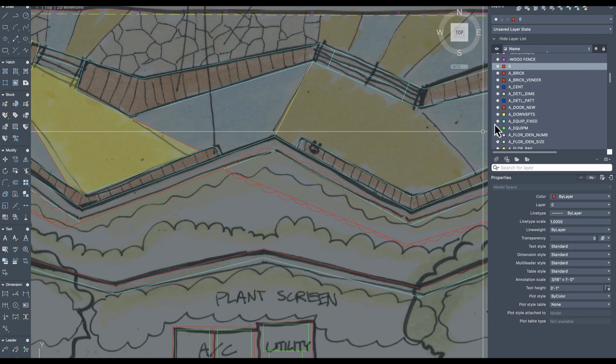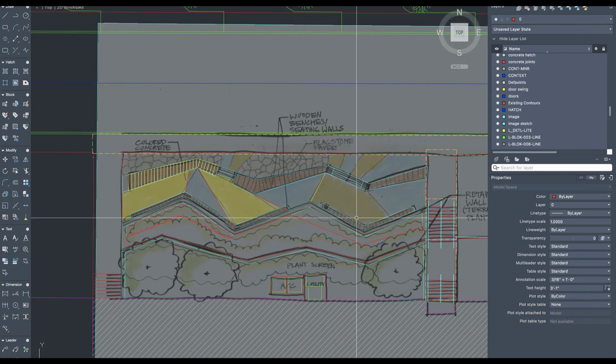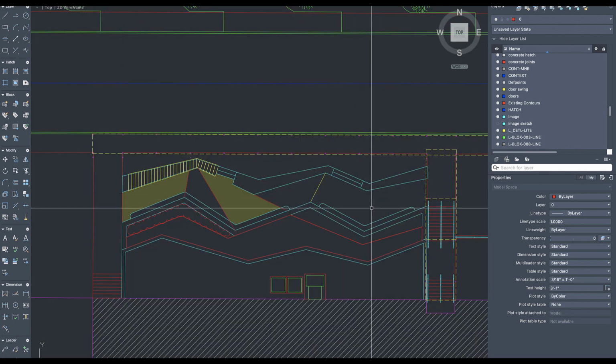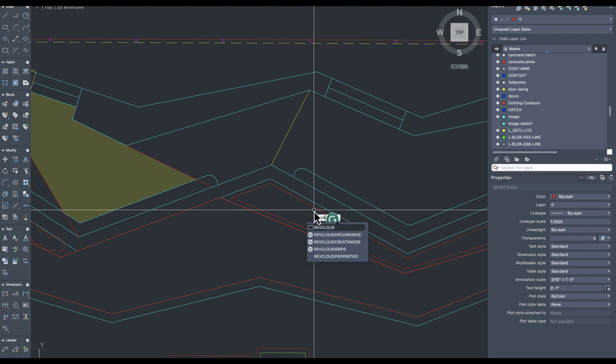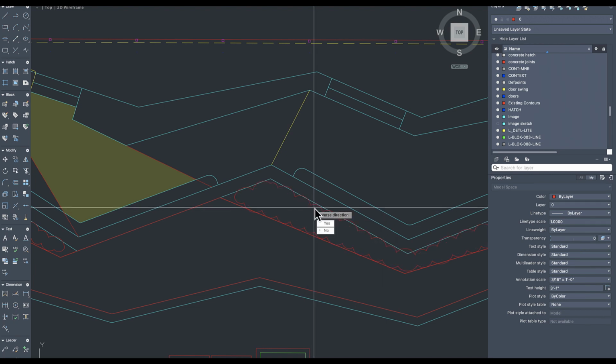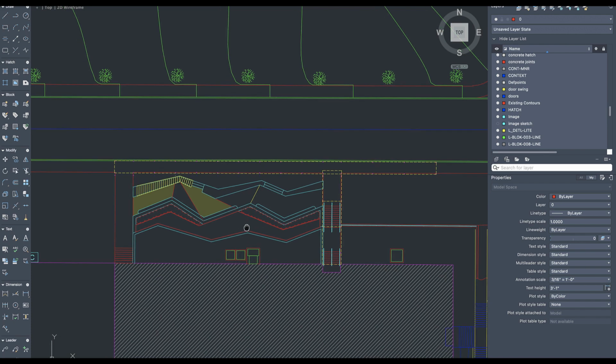So what I'm going to do is, let's turn off the image just so it's not in the way. I'm going to undo, of course I'm undoing the image, turn that off again. I'm going to undo and create that offset again, 6 inches, I think is what it did. Rev cloud, object, click on the object, reverse, nope. And now I can go back and erase that original object.